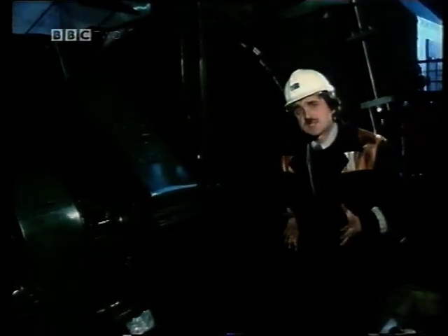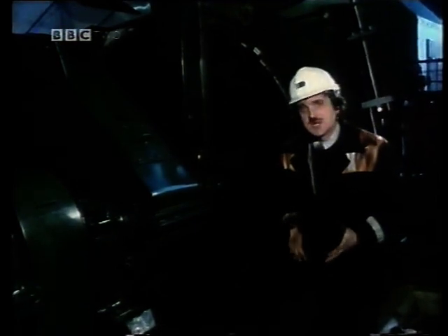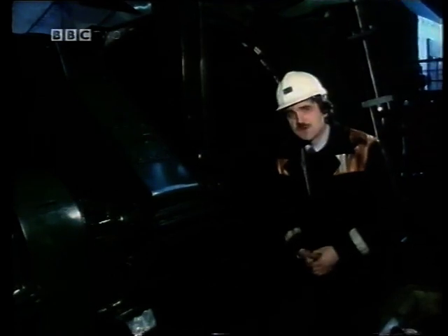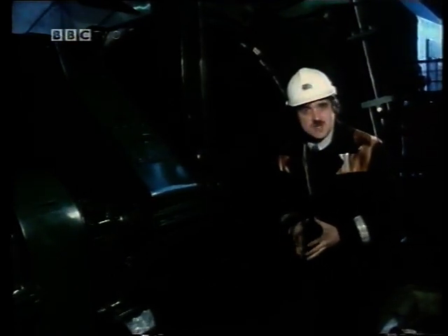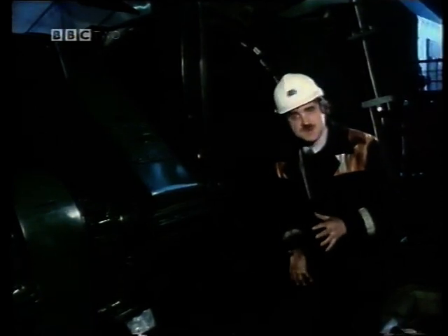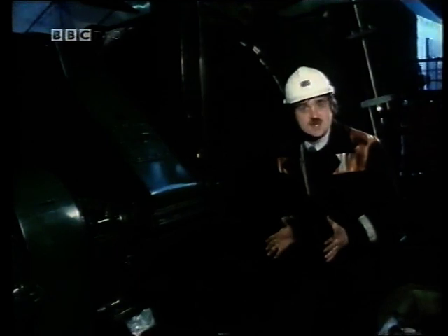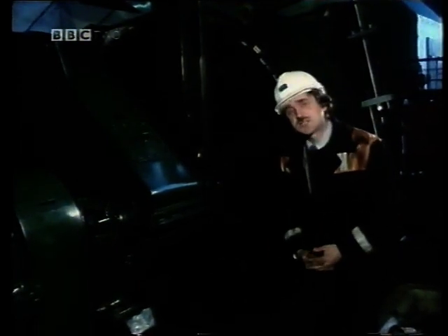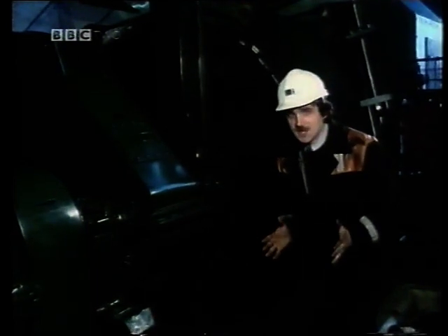So, we've looked at various factors which determine cage loading, rope and drum size, motor power and lift kinematics. But there is one final point. You see, the length of rope wound around the drum corresponds to the depth of the mine shaft. The deeper the mine, the wider the drum has to be in order to take the extra wrap. Well, in this mine, the mine shaft is 150 meters deep, and already the drum is quite wide.